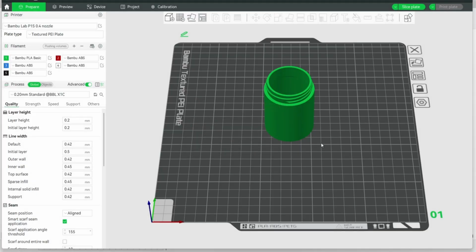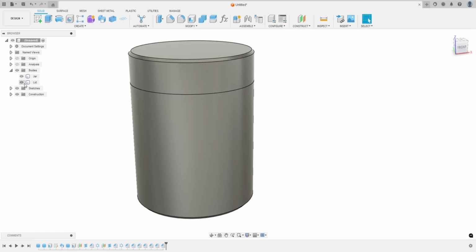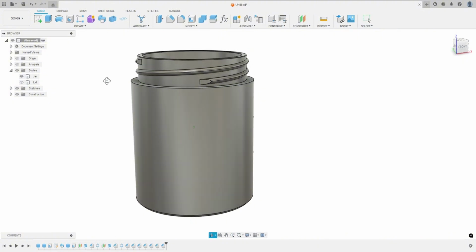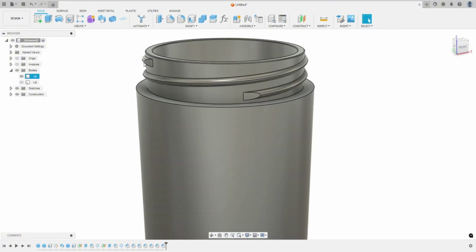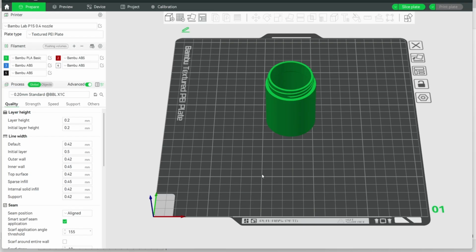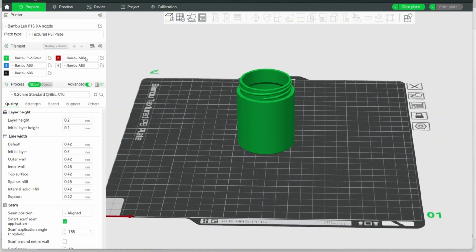The reason I'm showing you this is sometimes, depending on the filament you use, when you're screwing this on and off, it might feel a little rattly. That's just because of how this circle prints. It still works perfectly. It just may not be as smooth as butter. So how you can change that is add a modifier. We're doing a 0.2 layer height.